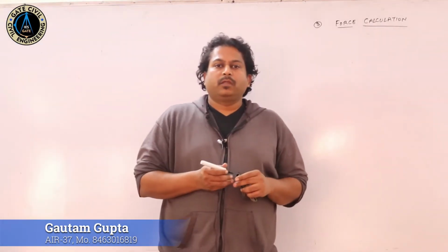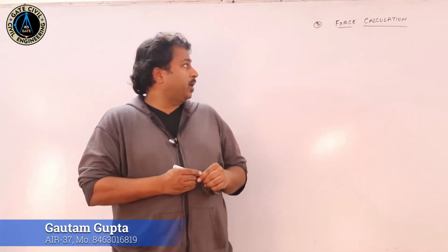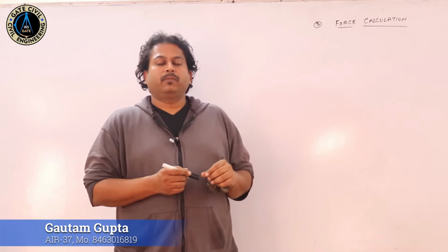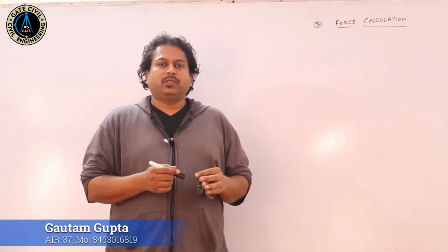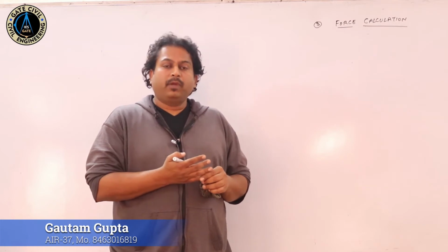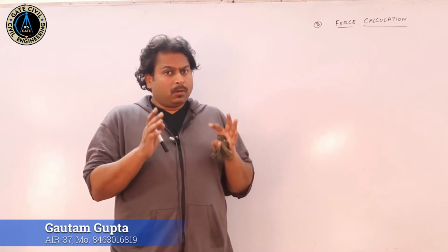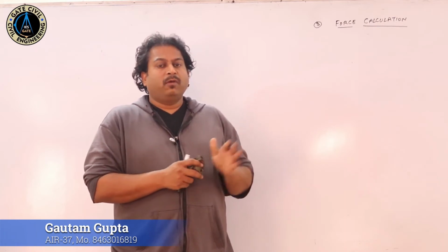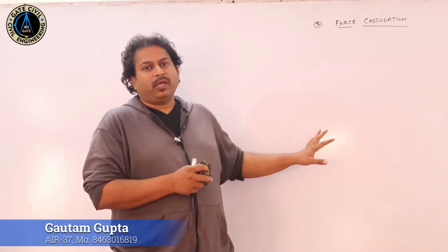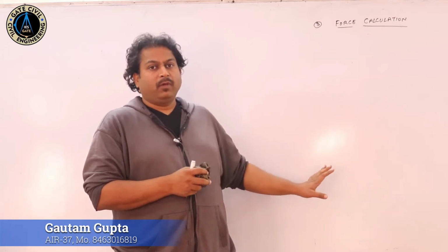After completing the given data and the sizing, we will come to the third point, that is force calculation. Force calculation involves the drawing of the bending moment diagram as well as the shear force diagram. Just to brief you again, till now we have not utilized in any part the load factor of 1.5.